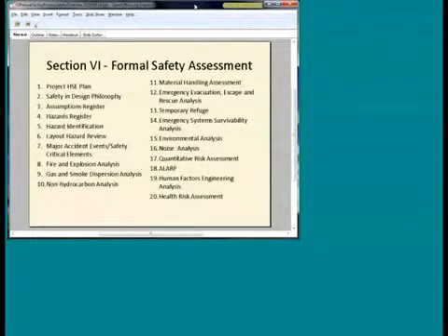Non-hydrocarbon analysis. Most platforms don't have a lot in the way of non-hydrocarbons apart from H2S, but they will usually handle skips and drums of non-flammables. Material handling, very important. Over 40% of accidents on offshore platforms are caused by dropped objects. In other words, someone drops something from the crane. You can drop it on the deck. You can drop it onto the service boat that's standing nearby. And if it's a big object and you drop it overboard, that's even more serious. In 10,000 feet of water, by the time it reaches the seabed, it's moving very fast.